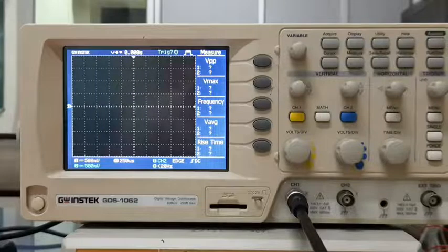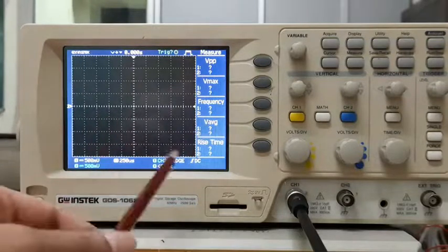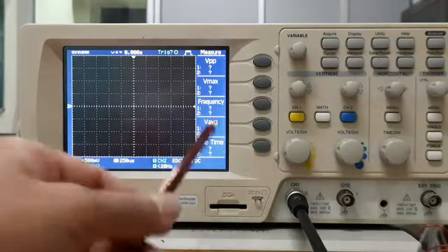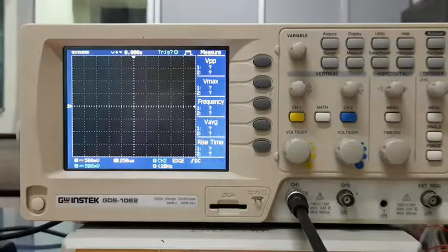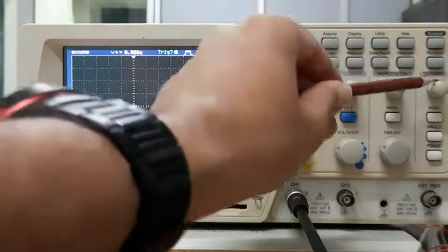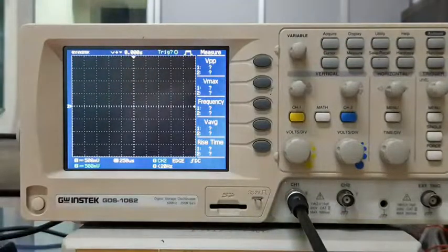So what it does, it keeps refreshing the data continuously, right? However, if the reference at which it refreshes the data is not correlated with the periodicity of your signal, then what will happen is you will keep seeing fluctuations here, right? And I'll show you how we get that. But you will keep seeing fluctuations here, and you will not be able to see a steady state waveform. So the trigger needs to be set properly, and the way to set the trigger is that, first